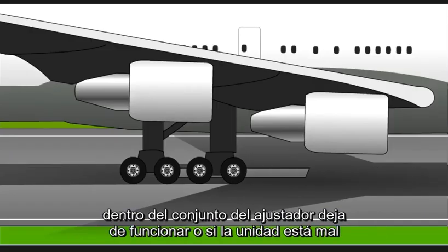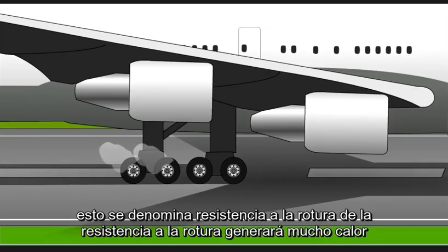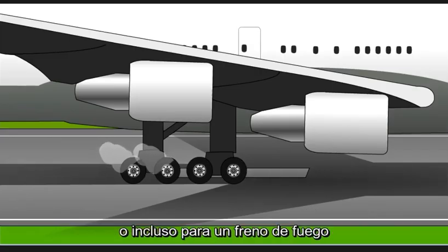If the return spring inside the adjuster assembly ceases to function, or if the unit is wrongly adjusted, then the brakes may not release fully. This is termed brake drag. Brake drag will generate a lot of heat and can be responsible for brake fade occurring sooner than it otherwise would, or even for a brake fire.